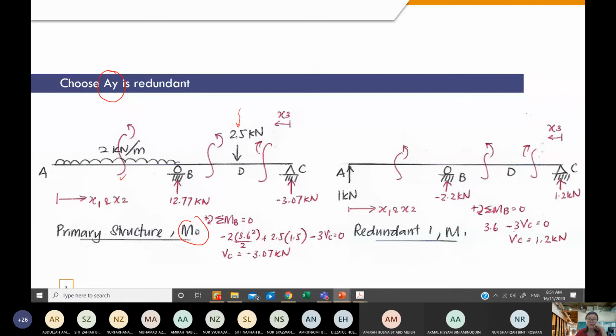But if you look at M1, in common practice you only need to cut 2. Still, please prepare the same sections as what you have for M0. Let's say maybe your M1 has more sections, 4 sections to be cut. Then in M0, you need to add another one so that the ranges of both are the same, and they start the X from the same place, with the same sign for the internal moments. Those are the 3 rules that I explained just now. So this is why the 3 sections have been chosen for M0 and M1.